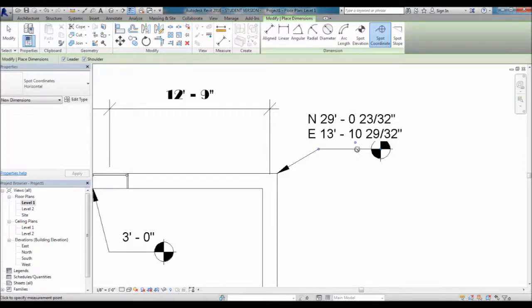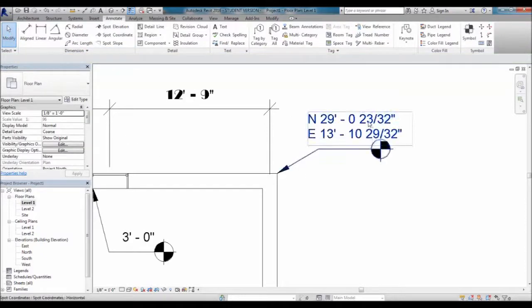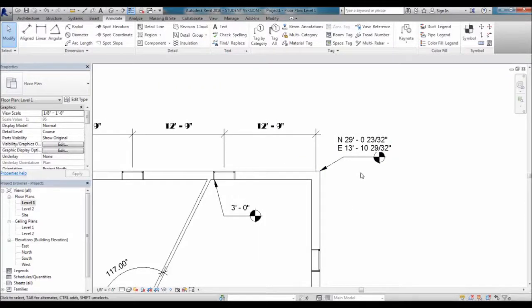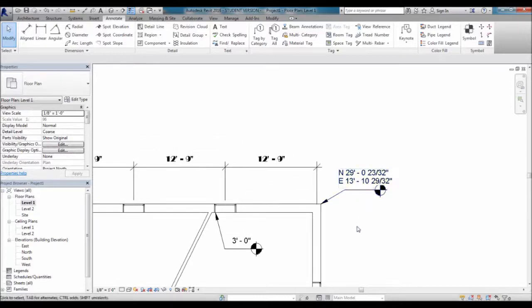Again, you probably won't ever have to use these, or you may not actually want to have coordinates for your building. But if you're going into greater detail and working alongside a civil engineer, and that civil engineer is going to plug these points for your building into a total station and some survey equipment, and go out there and lay things out based off of it, then you might want to have the most accurate coordinates for your building.